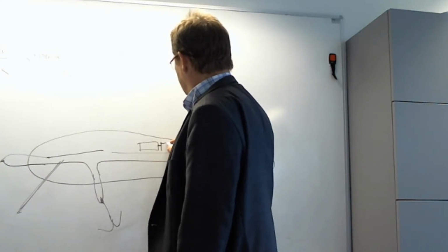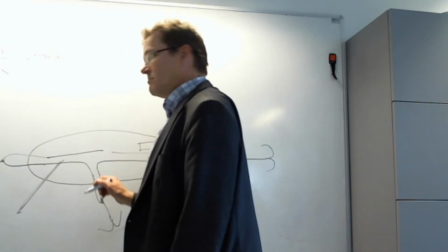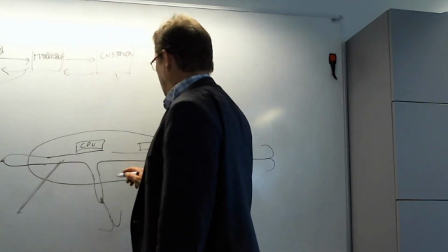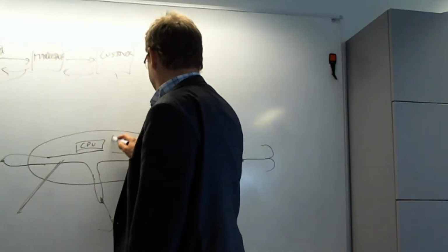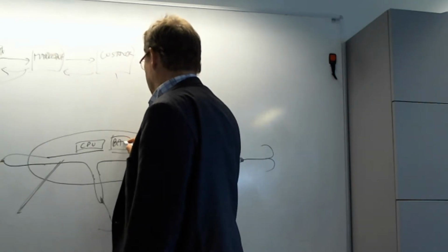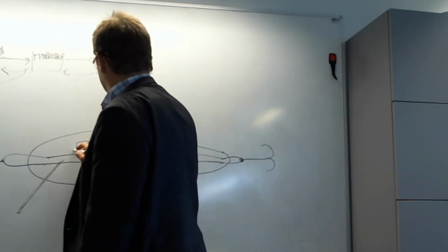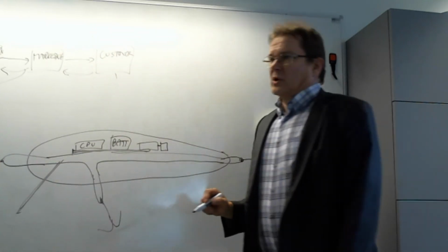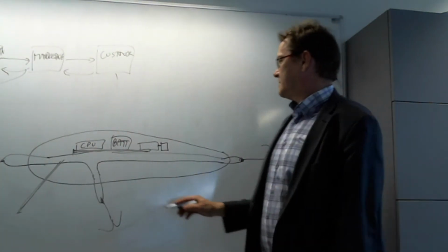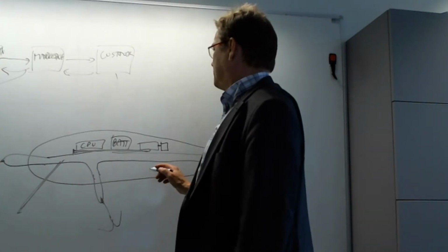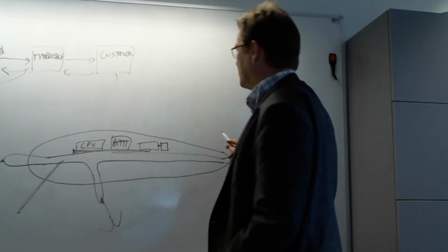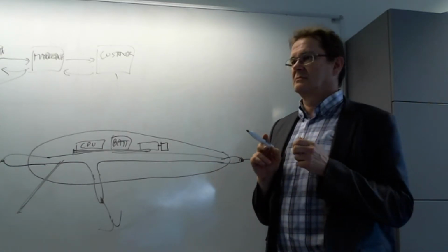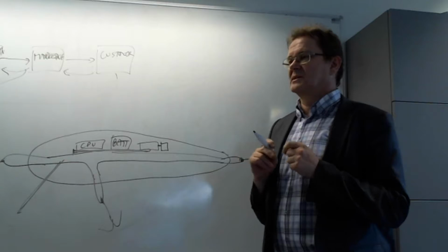So I thought, okay, I need to put a mobile phone vibrator motor here, which means that I need to have some CPU here. Okay, and then I need some battery and some other electronics, and all of this actually goes quite nicely on one circuit board, like that. Then there's a problem how to get the battery charged. You don't want any charging wires sticking out.